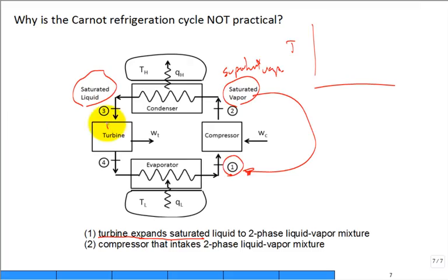So you just substitute for one of these. What did I just replace it with? Just an expansion valve. It'll drop the pressure. The refrigerant will flash coming through it. The pressure's a lot lower. The temperature will be really low coming out of that device. And that's the expansion valve.